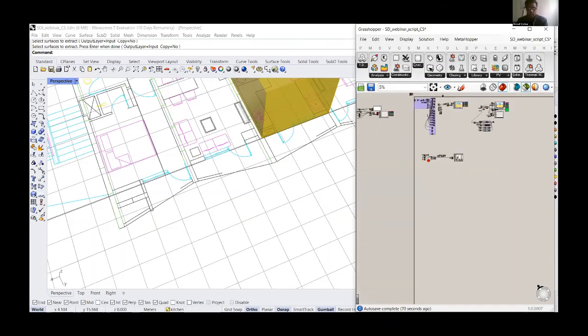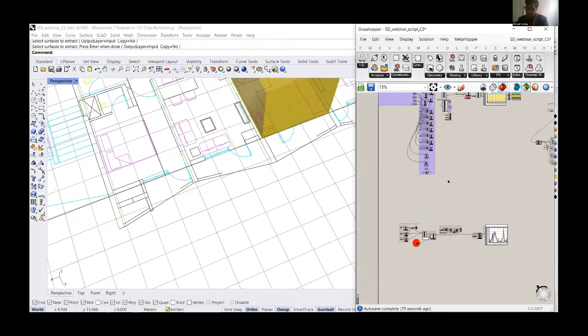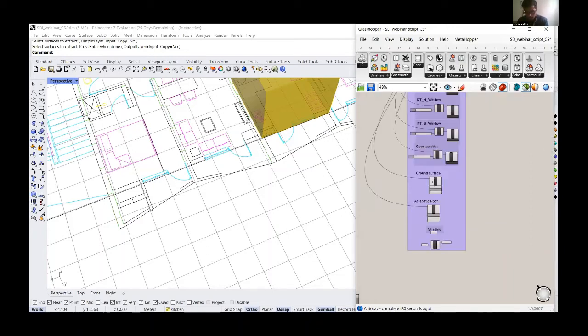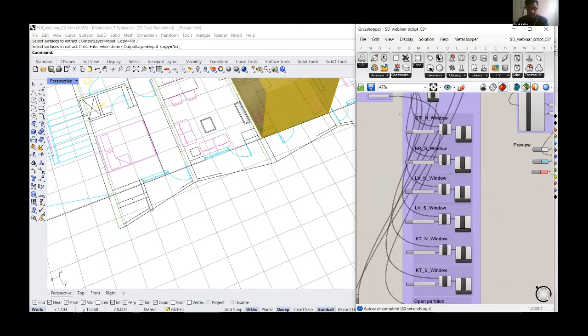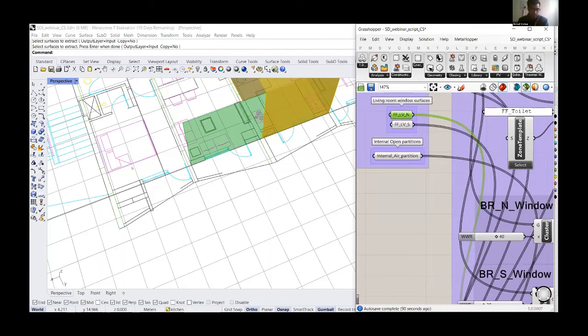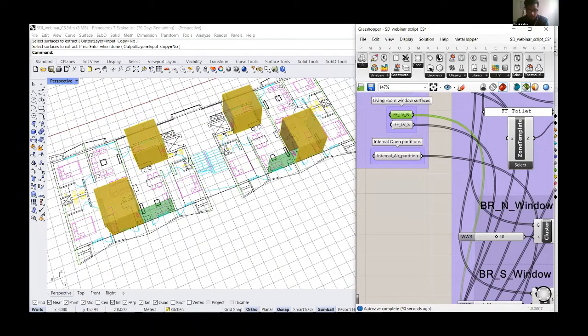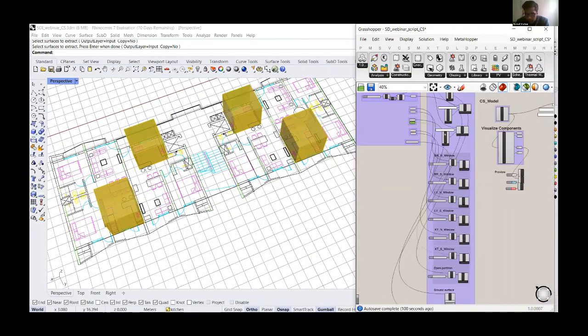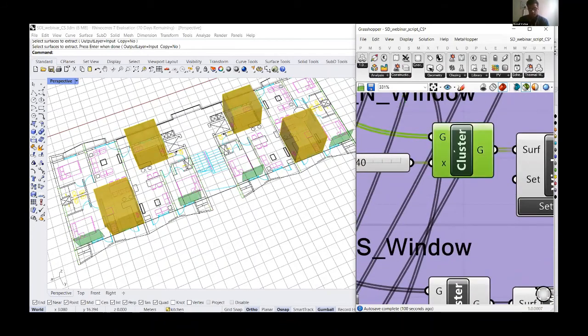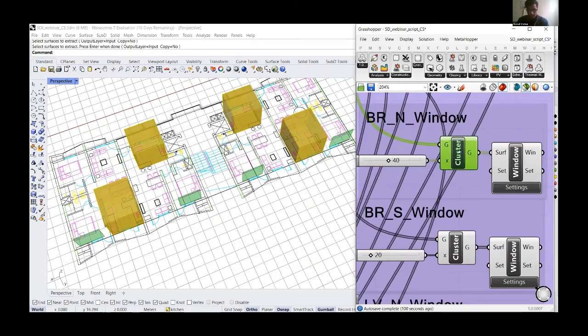Okay, so basically this is again a geometry modeling gimmick. If you are very well aware of Rhino and Grasshopper, you can figure your own way out to assign a glazing ratio, a WWR. What I have done initially, I had explained that I had extracted different window surfaces, basically the faces on which the windows will come. I had previously extracted all of them separately depending upon the orientation, and then I use this component which is available in the Climate Studio tab.